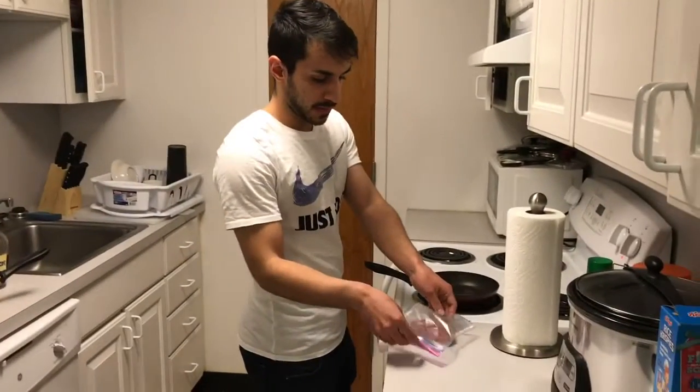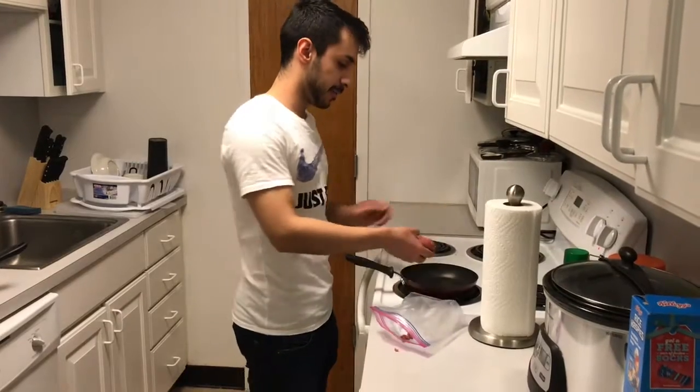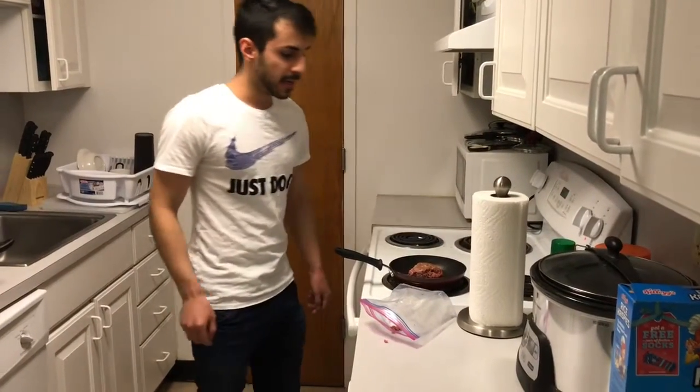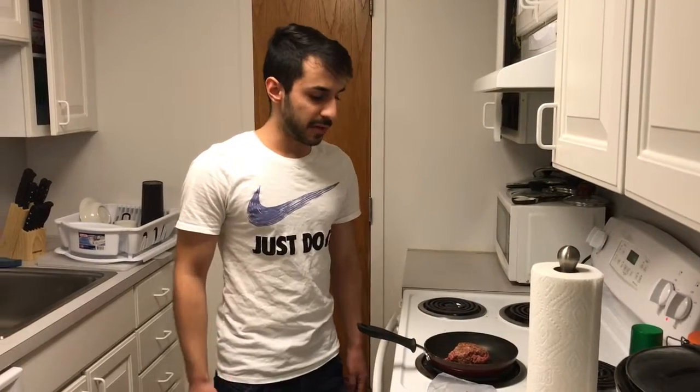Conduction is defined as the heat transfer due to molecular motion. In cooking, when you are cooking just a beef, for example, it follows Fourier's law, and to find the heat flux, you could just multiply the thermal conductivity by the temperature gradient, and that will give you the heat flux in watts per meter squared. And to find exactly the heat transfer, you just multiply it by the area of the plate.